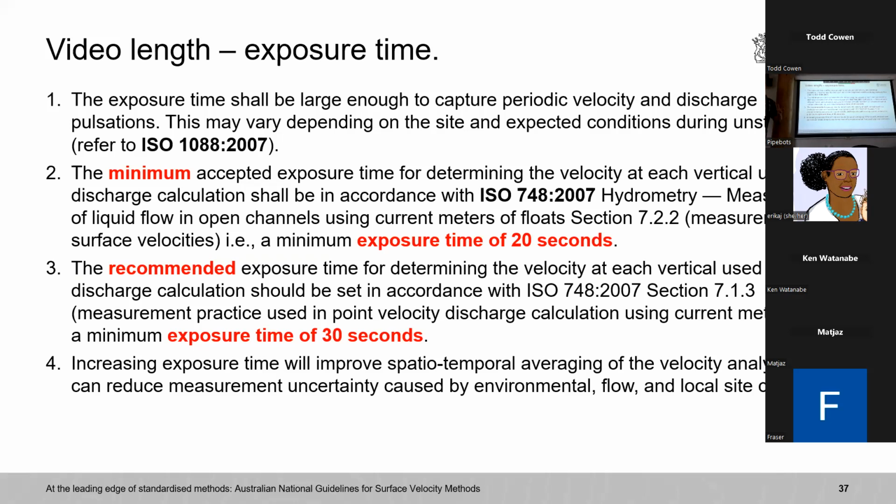We're finding similar conversations when we were setting the ADCP guidelines in regards to 12 minutes exposure time for your measurements. We have a lot of feedback saying, well, I can collect a decent measurement in 2 minutes. It's kind of not the point maybe here, but there is a standard and this is what you need to stick with. Similar conversations here, but having people not familiar with the imagery techniques, but been in the hydrometric business for a long time, quite adamant that we need to stick with the standards in place.